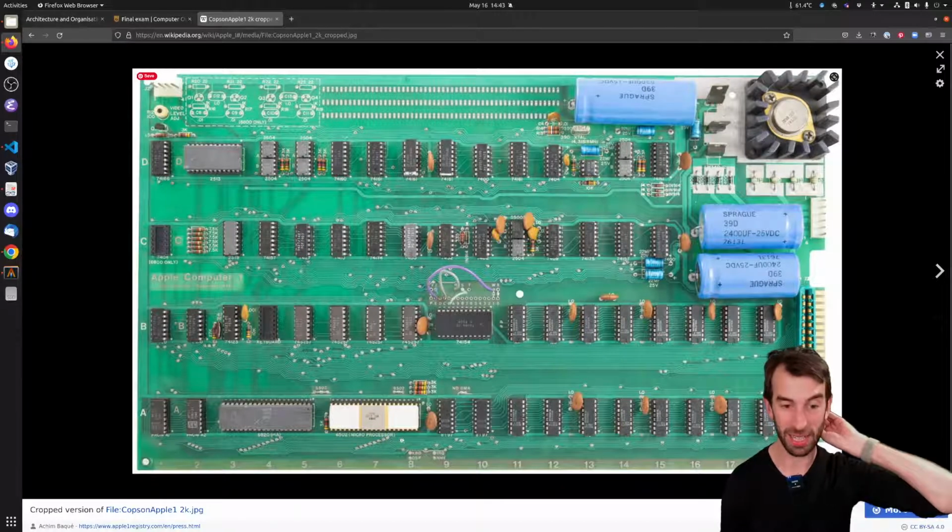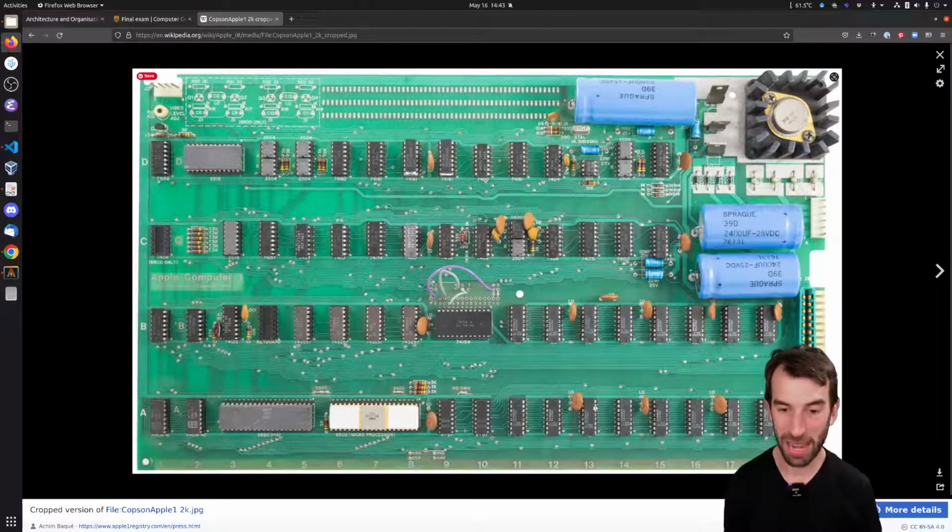And it has a 6502 microprocessor and a 6820 PIA. It's got some RAM. It doesn't have one RAM chip because RAM is expensive. Now RAM is cheap, but in those days it was expensive, and so it was cheaper to get lots of small RAM modules and put them all together and then work out the addressing logic with these other